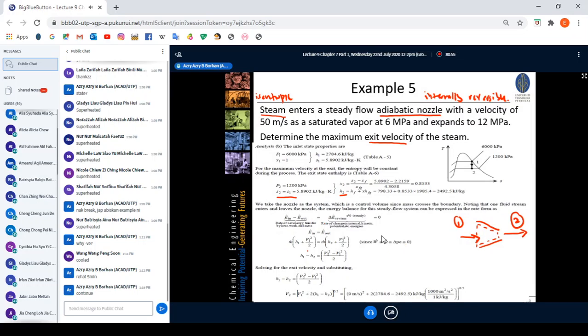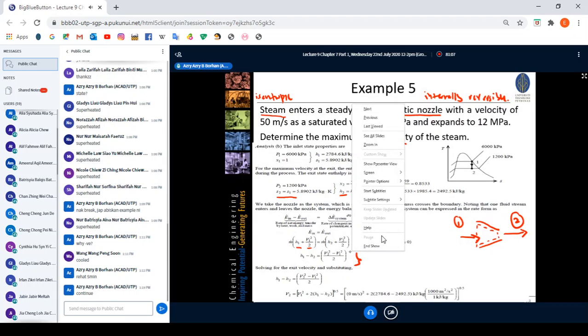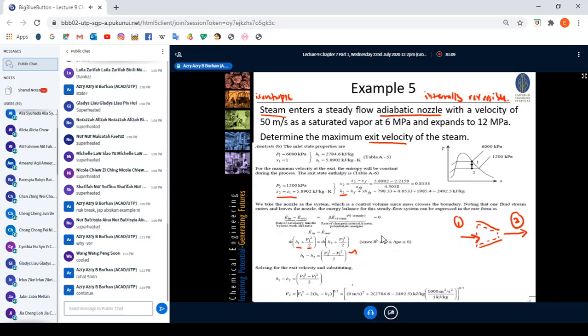So that means what's left is your mass flow rate on both sides, which is associated with your enthalpy h and also velocity, right? So let's say this is the final formula that you have. Remember, you simply key in the values and then simplify that to get your V2 here. Guys, remember, you need to show this particular conversion factor.